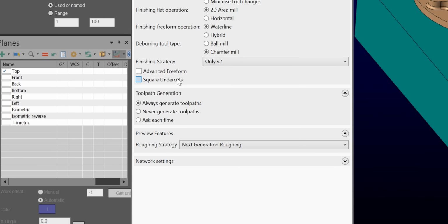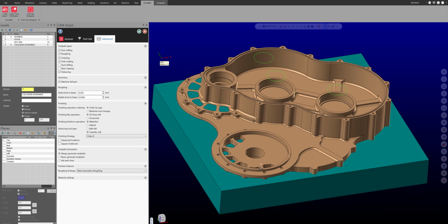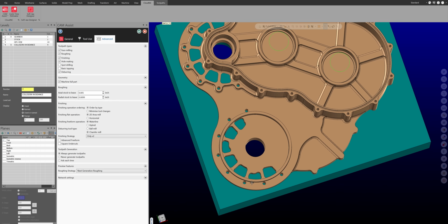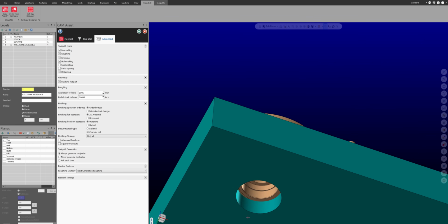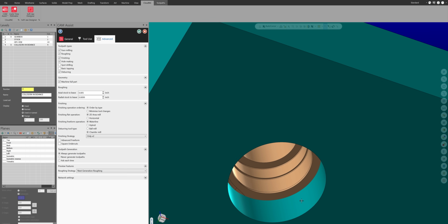Next we look down and we see, do you want to consider undercuts or not? Now you can see with this collision avoidance geometry that I've created, I've got 2 holes going through this part. I made those bigger than the hole that's in the part right now. So if we look on the bottom side of this, you can see I've got some material left on the part between the diameter of this collision avoidance and the part itself.